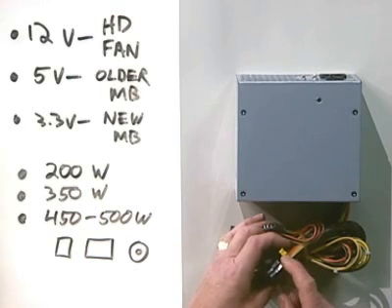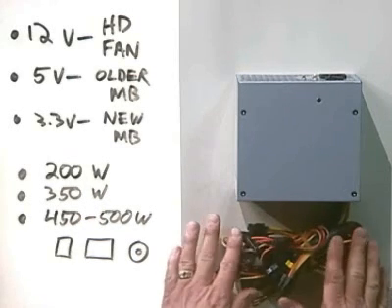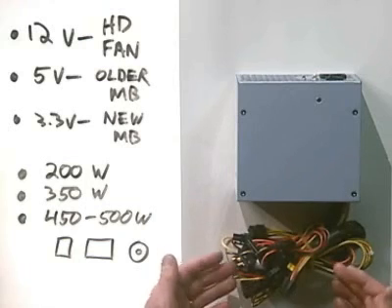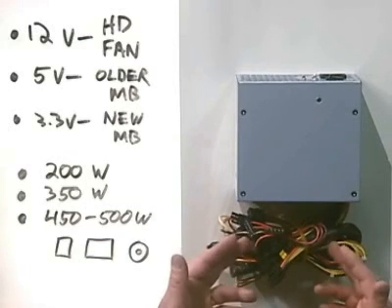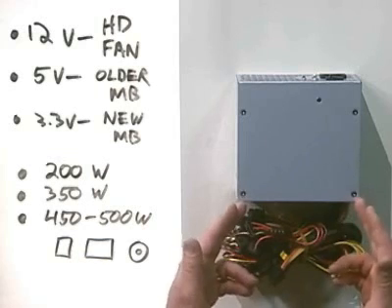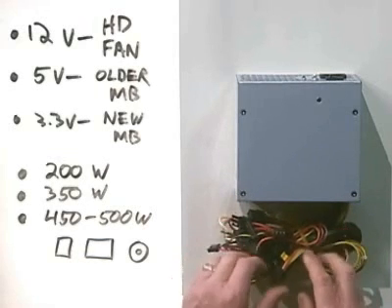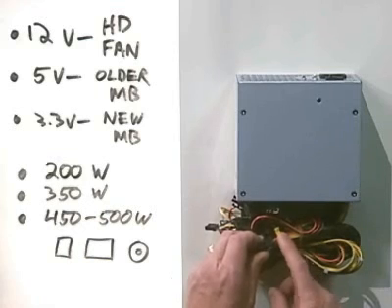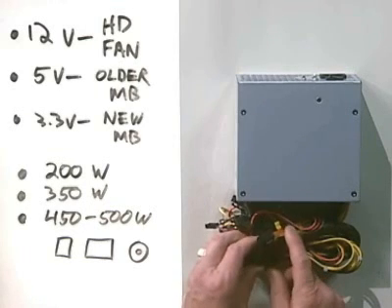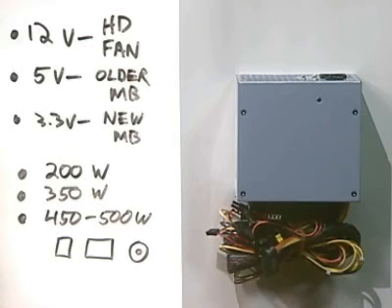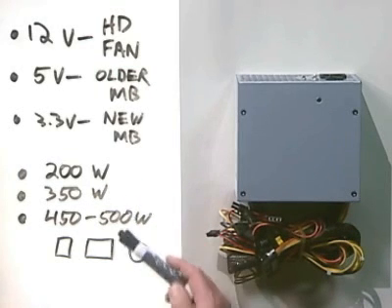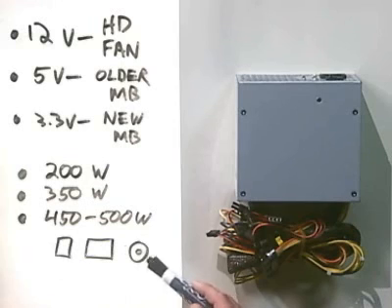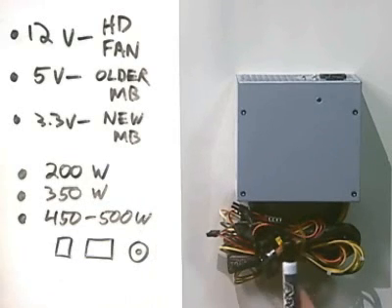This applies not just to the boot up process, but while the PC is in use as well. If, for some reason, there's not enough power to supply the demands that are being asked of the power supply, the current will be lost on the power good wire. When that current is lost, the system will shut down. That's why you need to make sure that you use an appropriate power supply. If your components are demanding too much current from the power supply, the current will be lost on the power good wire, and the system will spontaneously shut down or reboot. Losing current on this power good wire can be caused by a couple of other things as well.